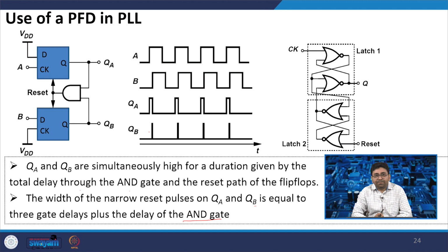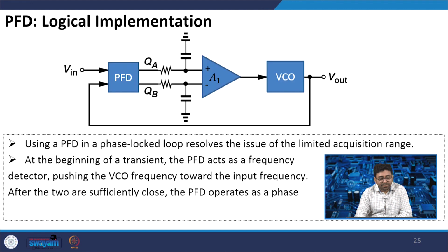So this is how we can implement the phase frequency detector by using a sequential circuit. As A is increasing, what will happen is that you will get a VDD, meaning D will be directly available at the output, and as omega B increases, you will get a QB which is raised, but the moment both are equal to 1, this will be reset. So this is how this PFD will work.